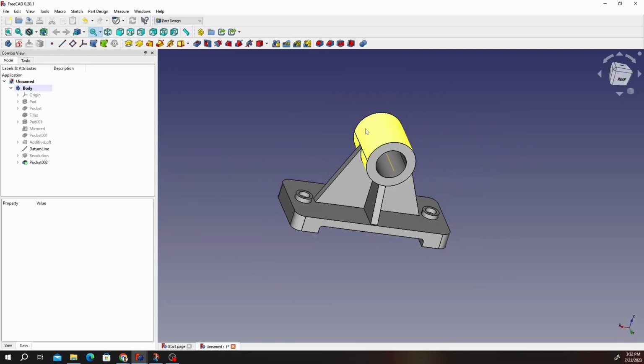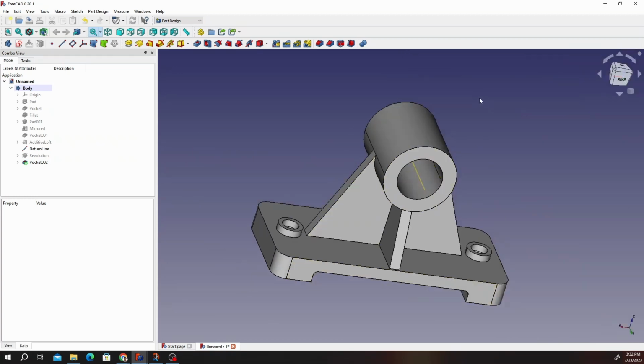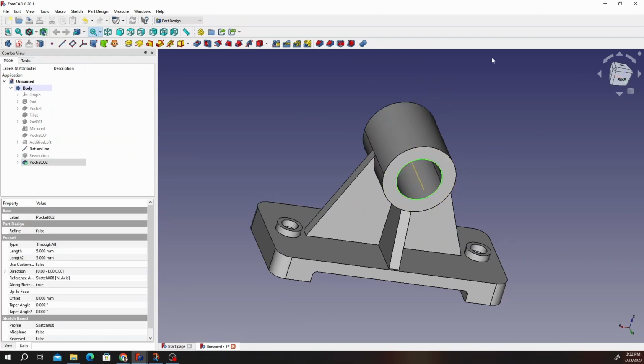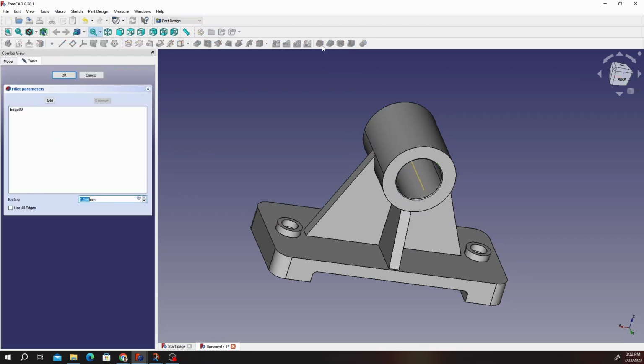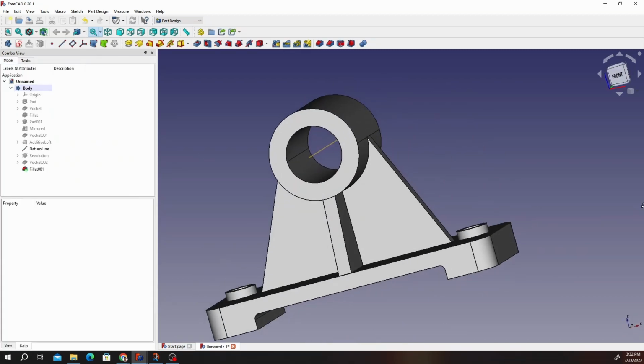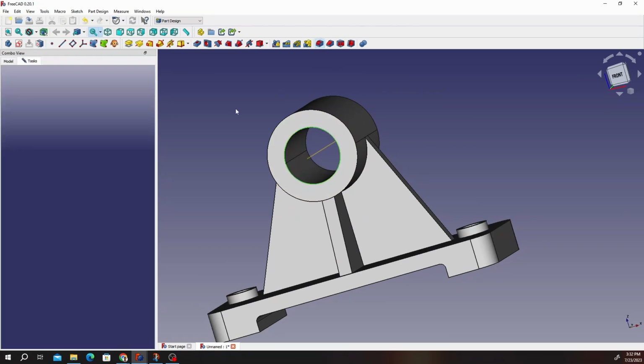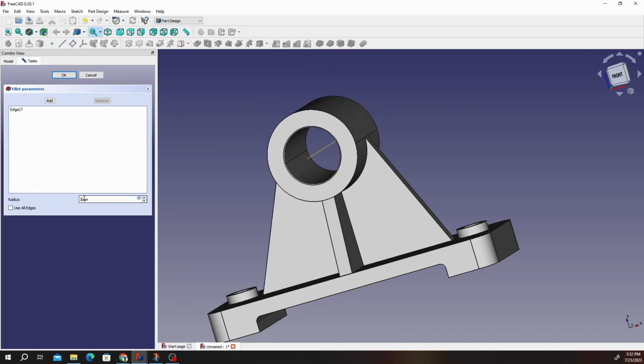And the other thing you can do is to make it look a little more realistic. You can always go and put on fillets and chamfers. For example, you can just click on that face, and let's say we're going to put a chamfer. We can increase that to 3, and then rotate it on the back. Click on that, give it 3.